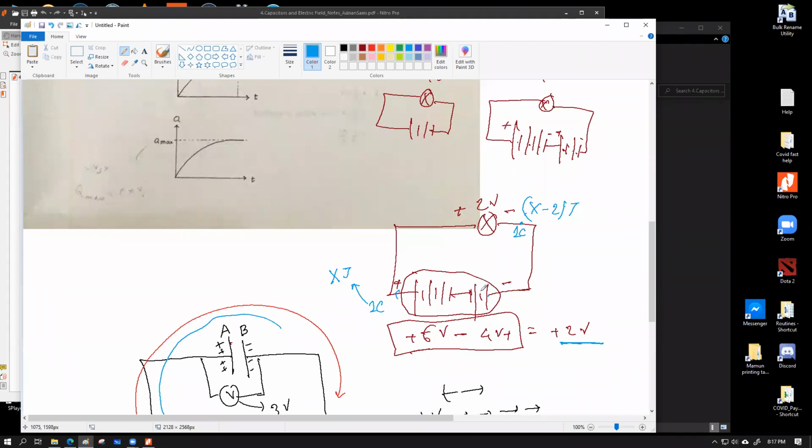Rather, this is going to try to absorb more energy out of it, because now the current is flowing through this battery in the reverse order, which basically is the base process of charging up this battery, which we've learned in the Kirchhoff's law process in our AS syllabus. So it was a relevant discussion there, which means whenever this 1 coulomb charge reaches this point, its energy is going to be X minus 6 joule, and it will enter into this battery.